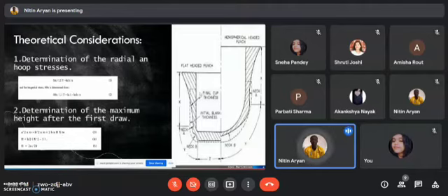1), and r is taken to be 2.2, which is the limiting drawing ratio, LDR. By substituting the value in equation 4, the maximum obtainable value of h is equal to 2b. That is, it is not possible to obtain a cup whose height is bigger than the base diameter. This is very useful for engineers and technicians in industries, because by looking at the drawing of the required part it can be decided if you can produce it from the first stage or we need a redrawing process.